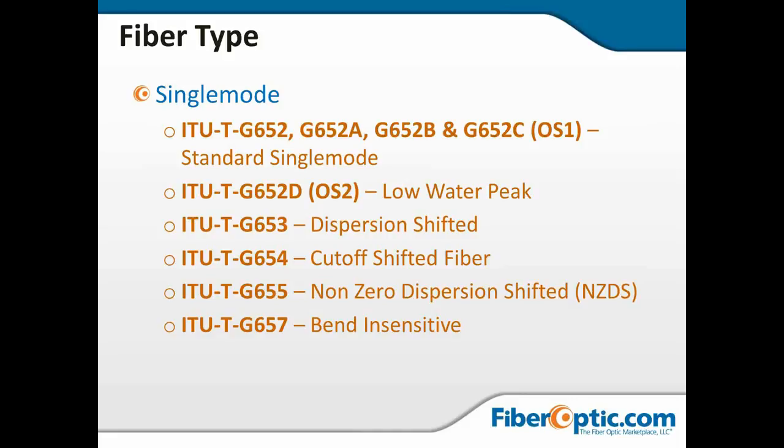So again, you'll see patch cords that have a bright blue color. It's kind of a darker blue, and those are the bend-insensitive patch cords. If you see aqua patch cords, those are going to be the laser optimized multimode. So just make sure you're looking at aqua or dark blue on those patch cords, dark blue being the bend-insensitive.